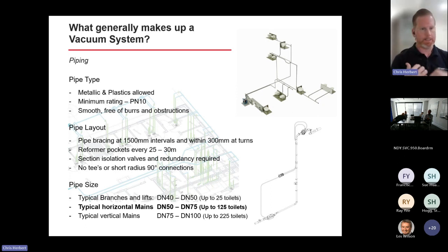So if you get radiant heat, say that pipe sitting outside in the sun, or you get some hot water in there and constant hot water, and you have maybe some inconsistencies in the extrusion of that pipe, you can have a point where the pipe collapses. Now, that's typically drain waste and vent, when people accidentally use drain waste and vent for vacuum systems. But for the most part, for PN10, globally, we've never had an issue with collapsing pipes, and that's why it's in the standard.